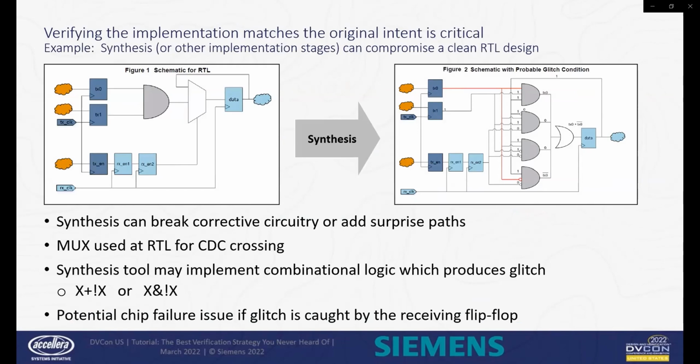However, during synthesis with power, performance, and area constraints, requiring significant transformation of the design, it's possible to have a netlist of the design still be functionally correct, but be timing sensitive to transitions. In this example above, the synthesis tool has built a logically equivalent representation, but timing races between the two paths highlighted in red may result in offset transitions on the final OR gate design that will create a glitch. This glitch, if sampled in the downstream flop, will result in metastable behavior just as if it had been a poorly designed synchronizer.